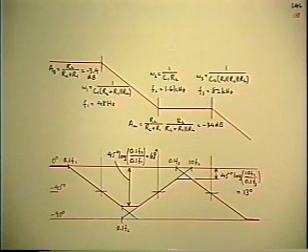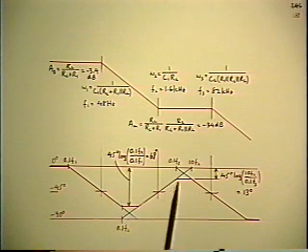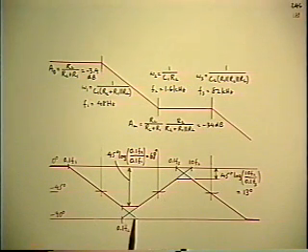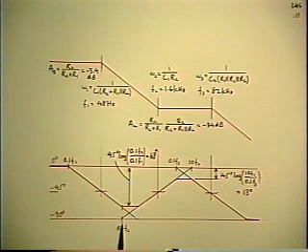Now again, subject to the limitations of homework problems, you have to constrain it more than that. So I tell them, change only R2. Because R2 determines one of these corner frequencies, so I can change the overlap.